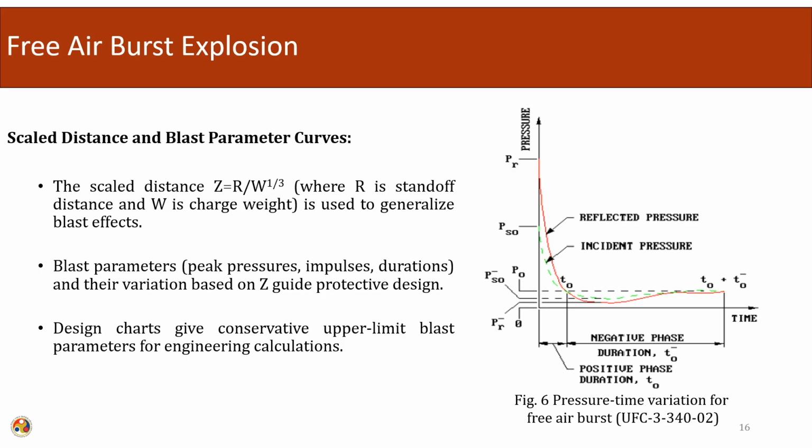Last time we saw the scale distance and the blast parameters. We established a parameter called the scale distance, which tries to establish the equivalency of the blast pressure in terms of the standoff distance and the weight of the charge. These parameters, peak pressure, impulses, durations, can be used for the design of the protective structures, and from here we can construct the design charts.